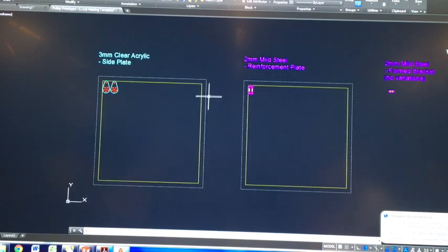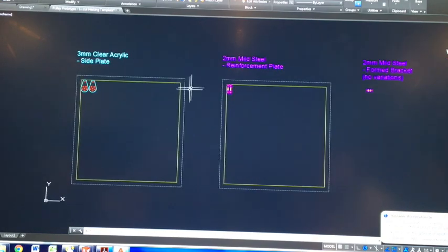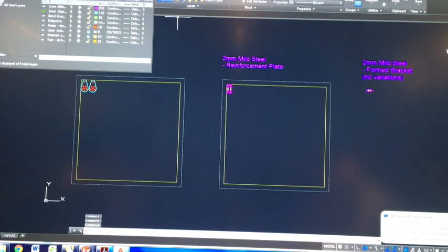Next up, you set up the layers. Now, for you guys, you don't need to set up the layers for this project, but for future individual projects you would want to do something like that. So, how to do that? On the screen here, in the middle at the top is Layer Properties. Click that button, and that will open up this pop-out window.